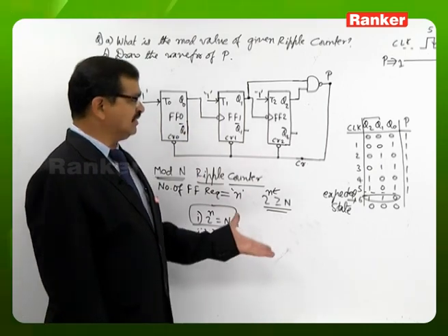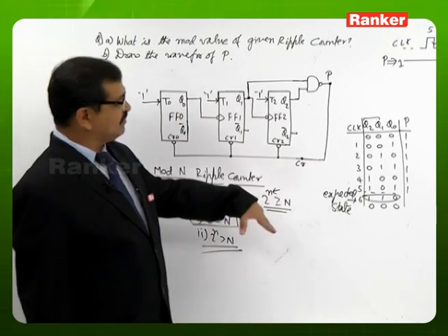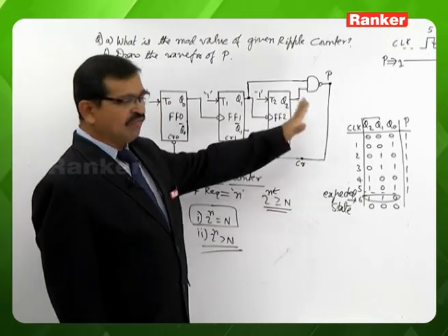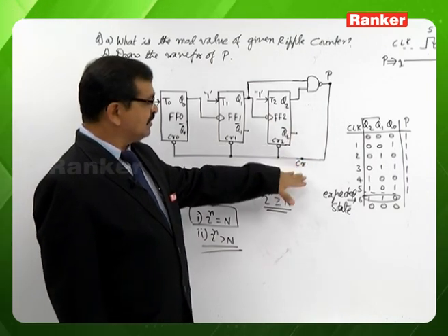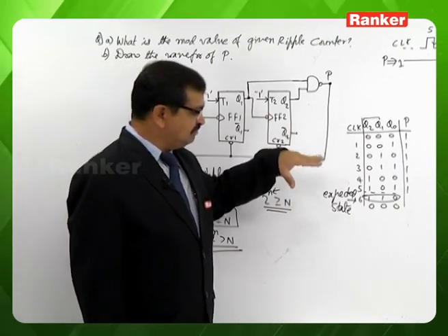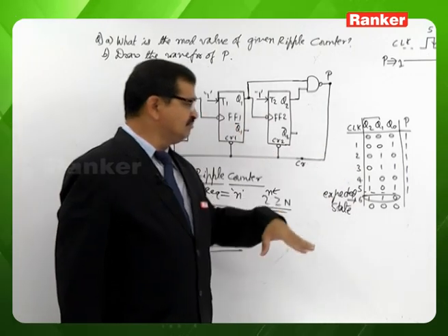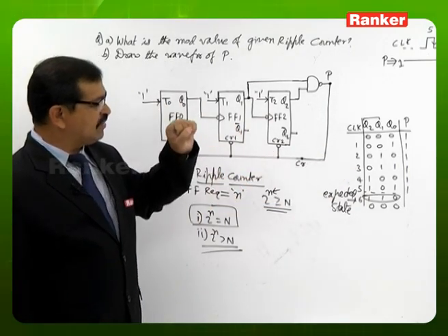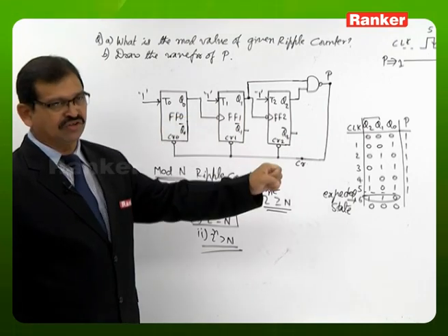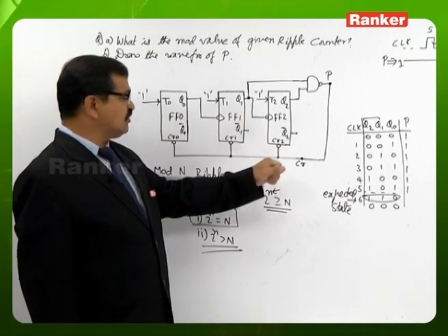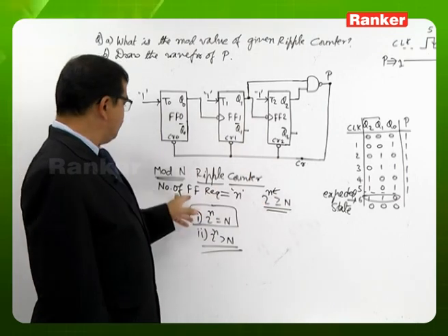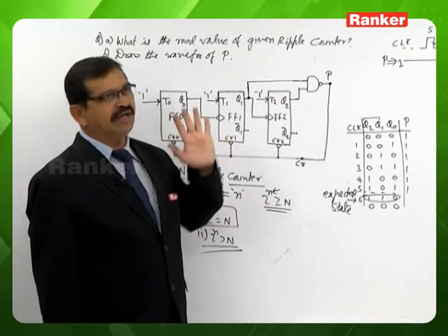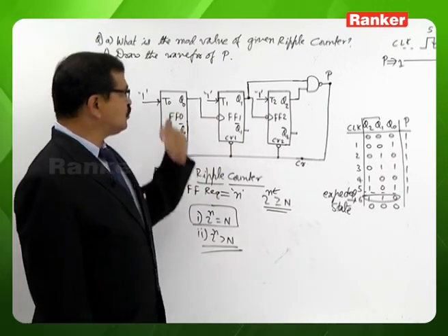That is required because by using this AND gate, we want to stop the clock counting. So by using this AND gate, we are giving a disturbance in the normal switching sequence. The normal switching sequence disturbance will be at this nth clock pulse. So for that purpose, we are using an AND gate. Okay, so we need to use an AND gate.